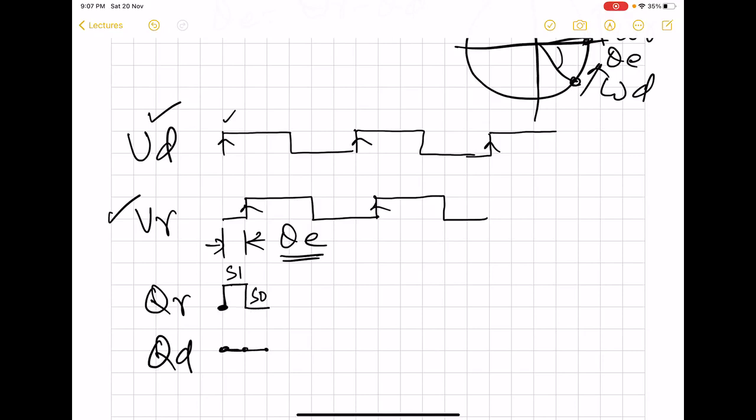And after that, we will have to wait till this moment, because this is where the rising edge occurs. So keep in mind that this state machine only senses the rising edge, and it does not react to the 1 or 0 levels of these two signals. And we need not do anything else to create a pulse for these signals. The system itself is inherently sensitive to the rising edges.